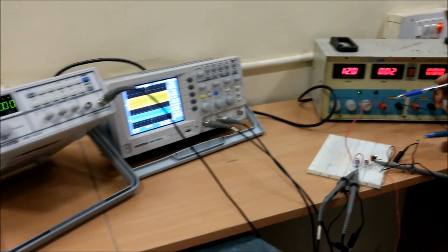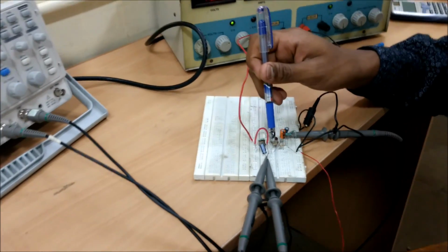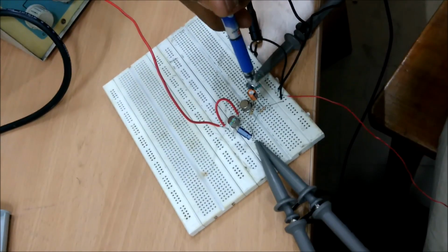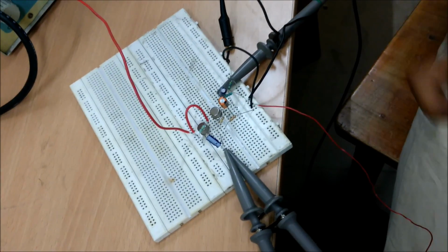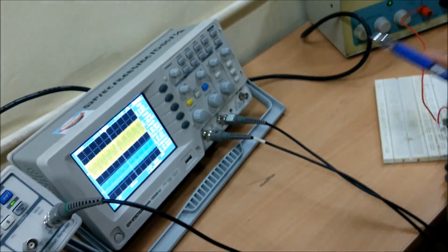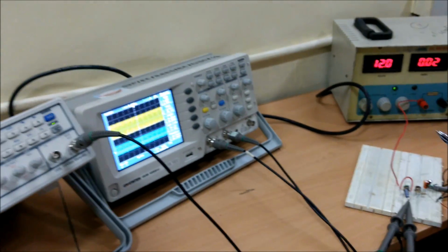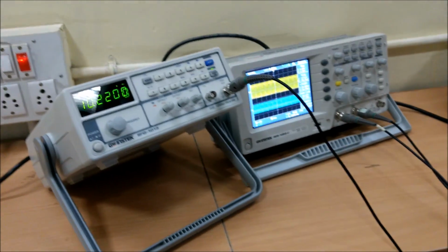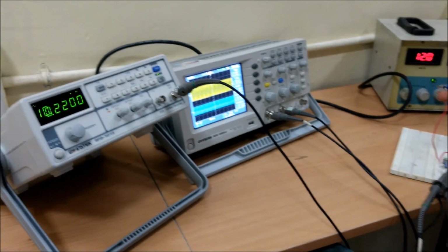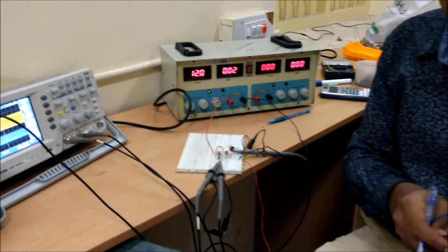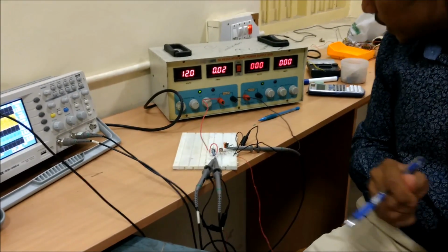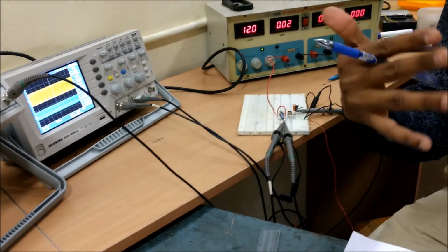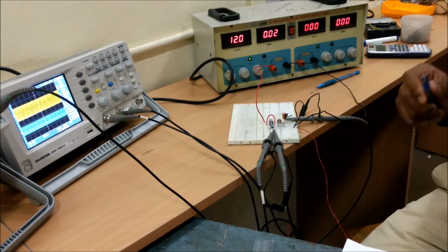Okay, the bootstrapping circuit. This is a bootstrapping circuit where I connected from the base a 100 kilo ohm. I used a capacitor of 47 microfarad. We can see that almost input is equal to output. Input is 4.6 volts and output is also 4.6 at 10 kilohertz. There's no load connected. Let's connect a 1 meg pot with a series of 100 kilo ohm and 220 kilo ohm. It's above 500 kilo ohm.